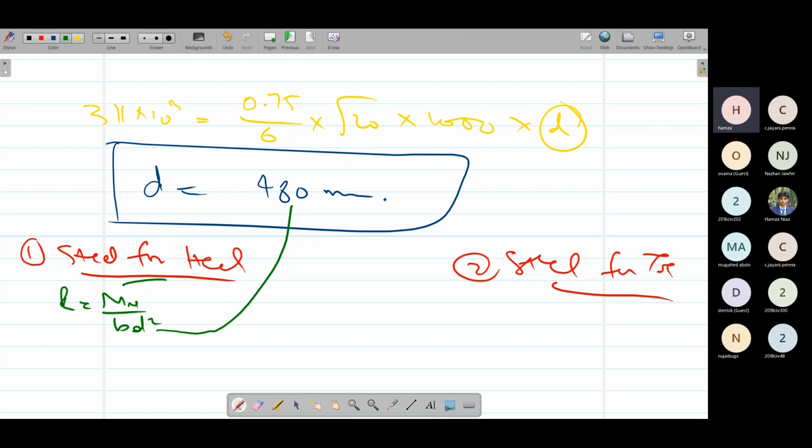Because we were not sure about this D value, whether the D value is changing or not. If the D value is changing, then our steel area would decrease. So that's why we are calculating this steel at the last. Then rho is simply omega 1 minus under root 1 minus 2.614 R over fc dash. And the last thing is As is equal to rho B D.